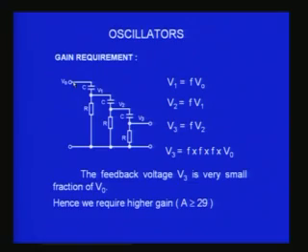Why is it so? To explain that, I have shown you a circuit on the screen. You are feeding the output voltage to this network, which has a potential divider with two components, one reactive and one resistive, and you take the output across the resistive component and connect it to one more RC, then take the R output and again connect one more, and so you have 3 stages of potential division. You divide it once into V1, then again into V2, and again into V3.